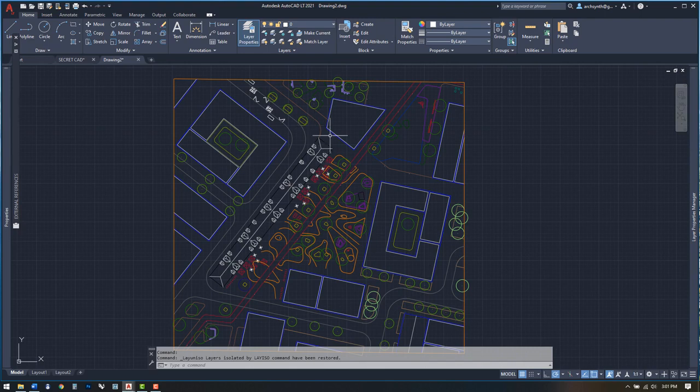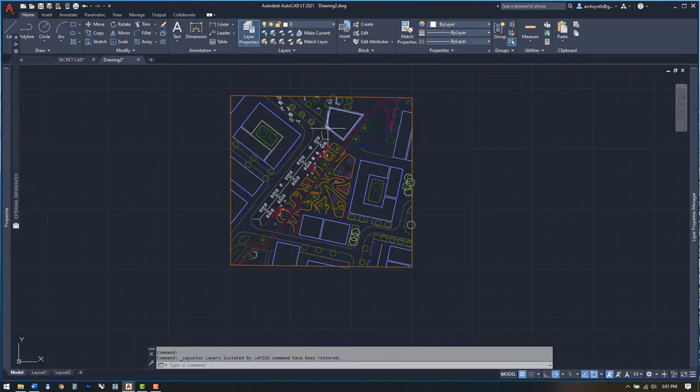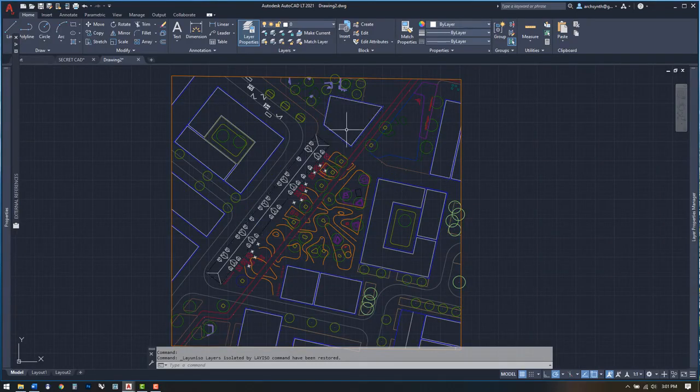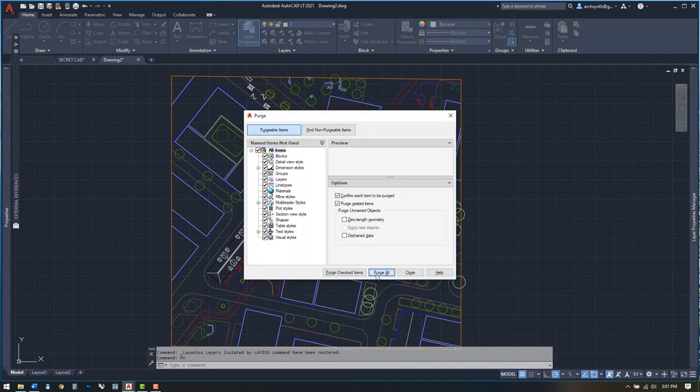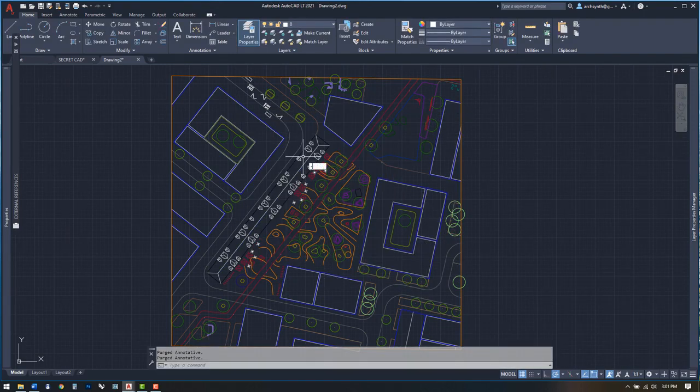I don't remember exactly where I picked this up, but it works a treat to eliminate overlapping lines, get rid of extra objects that somehow make it through the process, and generally gives you a very positive feeling of taking out the trash. Start with purge, PU. Click here and purge all. Close. The next command is -PU, which is a secondary menu with more extensive options.